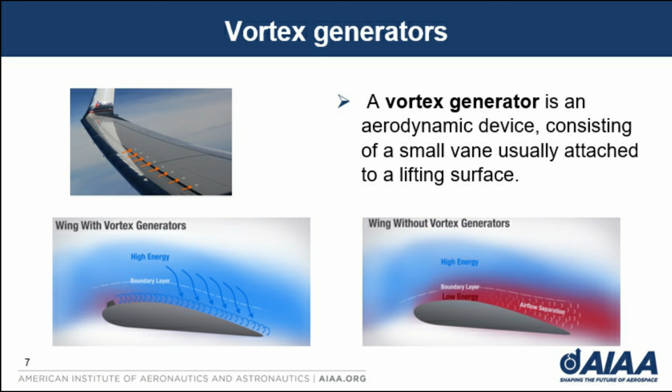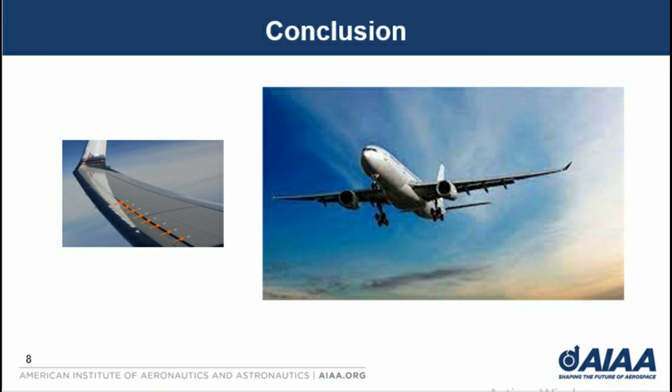At high AOA, in the outflow region, the detachment is thicker and the wake is deviated towards positive Y. As expected, through the inflow region, the flow is maintained attached and thus large incidences can be achieved without stall occurrence. This is one of the most practical methods used for boundary layer control because of the simplicity of this method. In conclusion, we see that this area in aerodynamics still needs some improvements and new ideas to improve the boundary layer control.